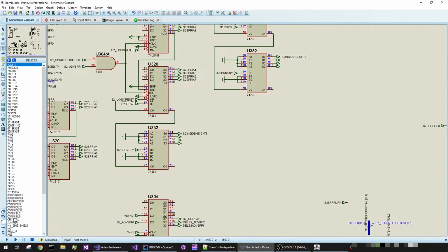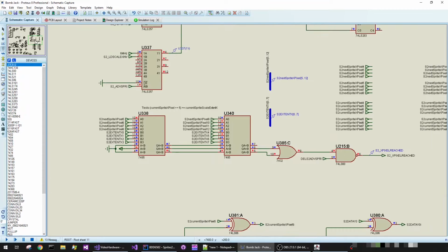So that basically covers the logic. The only part that really needs to be talked about after that is the current sprite X pixel coordinate range check. Again, we're doing the select starting at signal 5, bit 5, so we're automatically doing the shift down already, and we've got a couple of comparators here cascaded, and we're looking for equal to or greater than.